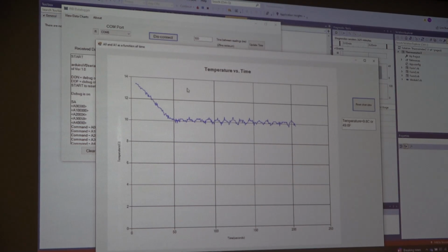It doesn't really work for this example, folks, only because this is not a highly dynamic system. If I had something like a brush motor with an encoder, rotating really quickly, absolutely, D becomes critical. In long-time constant control systems, you don't need derivative. As I showed you up there, as long as you're not too heavy with your I, you're all good. You'll hit set point, you'll stay right there, everything's good. Okay, it's only in highly dynamic stuff that you actually need D.